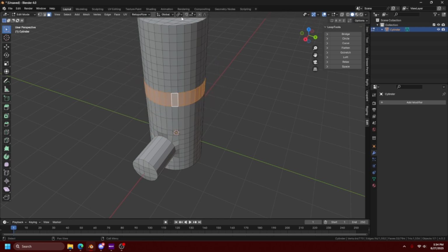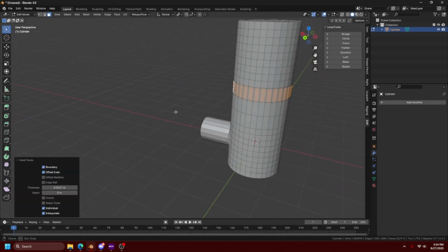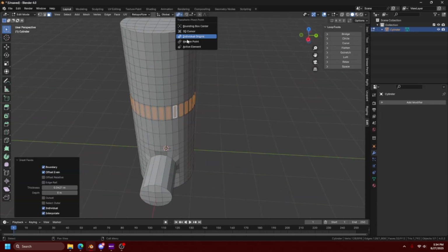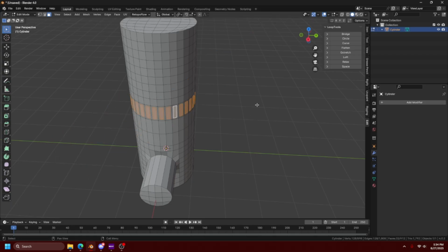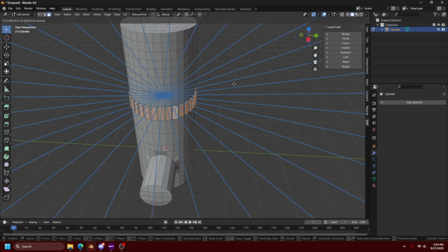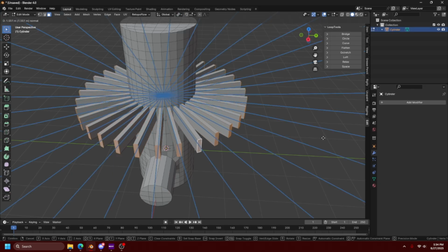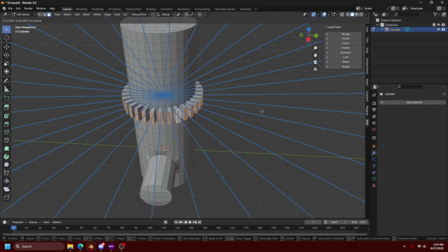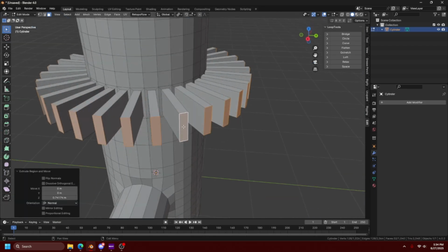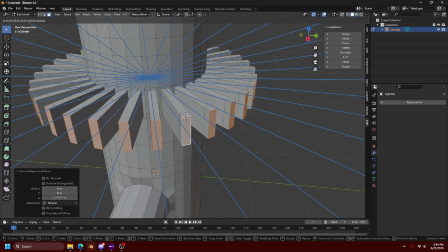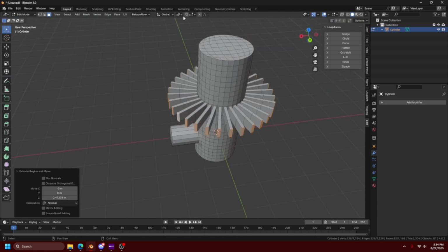But something that you can do is change that. I use this one a lot, individual origins. Let's say I had a bunch of faces and I wanted them to all extrude. If I had that at median point, the extrude for all of them is going in one direction, and that's no good. Instead, I can change it to individual origins and look at all the lines. It's so beautiful. All the extrudes will go based on the individual origin. So each selection is treated as separate. Each box is taking the middle of that box and then extruding from that. So super good for individual origins.